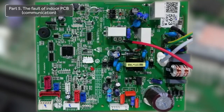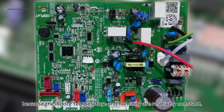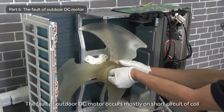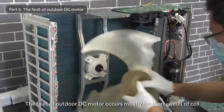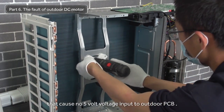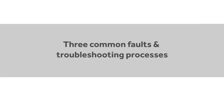Part 5. The fault of indoor PCB communication. The communication fault of indoor PCB is rare because the indoor temperature and humidity are relatively constant. Part 6. The fault of outdoor DC motor. The fault of outdoor DC motor occurs mostly on short circuit of coil that causes no 5-volt voltage input to outdoor PCB. 3 common faults and troubleshooting processes.